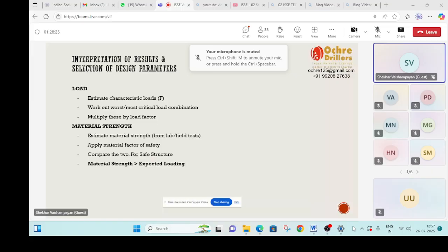Is there something called FCK for soil? The answer is no. Because in the concrete casting, you test number of cubes, not one. At one batch you test 6 cubes, and you go on testing cubes like that in the quality control, and so you have very good idea how much is the minimum material strength or you have defined it beforehand.